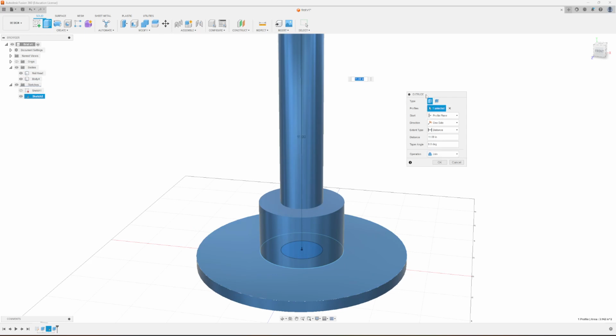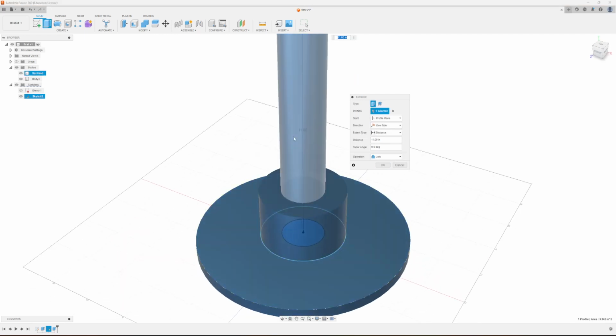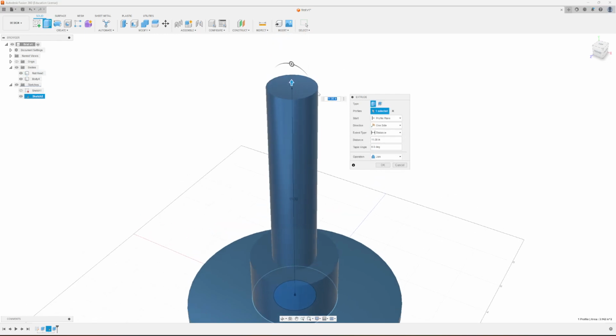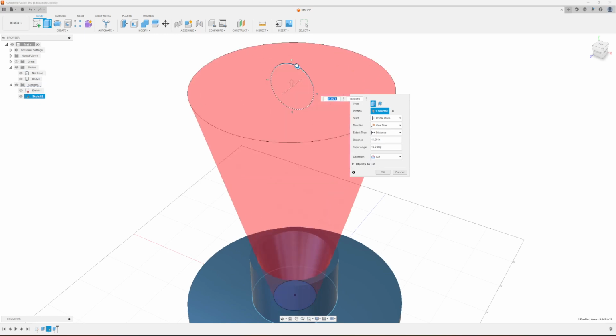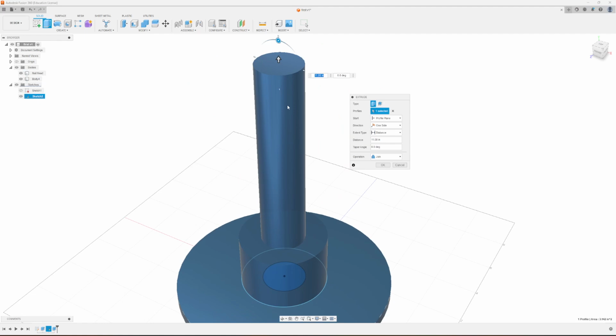Now we're going to go back here on the extrude panel, the window that comes up whenever you click extrude and then click on your object. So we have the start again, which is the profile plane on top of the nail head. The distance, which we just gave it 11 inches, and the taper angle, which we could change. See how it's really drastic because it's so far. We're not going to do that, but you can change the taper angle. Every once in a while I use this. I very rarely do this because I would rather modify the object rather than do it in the extrude.